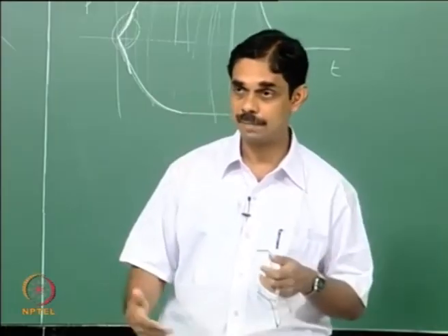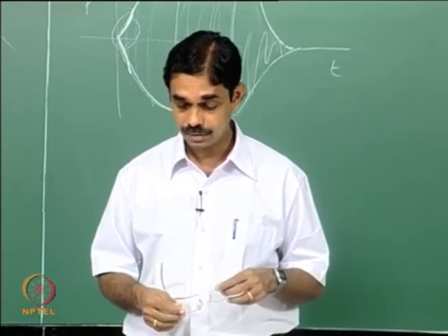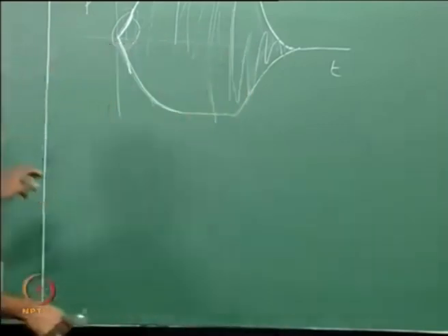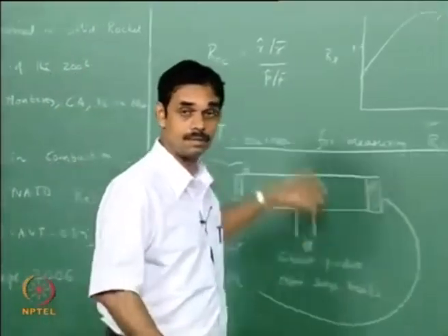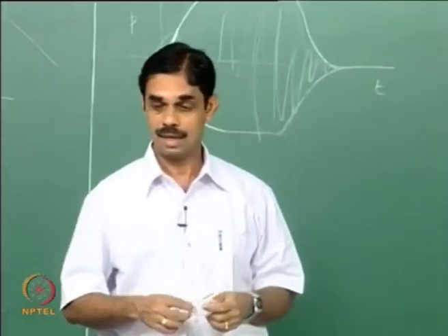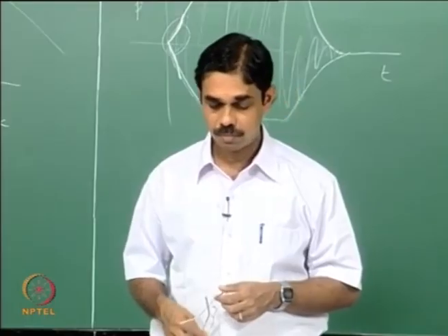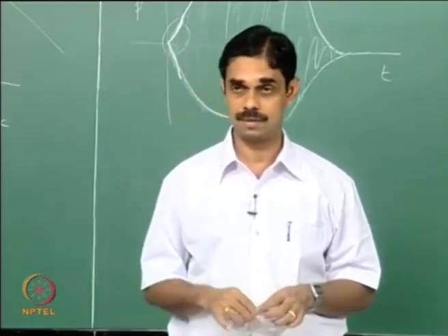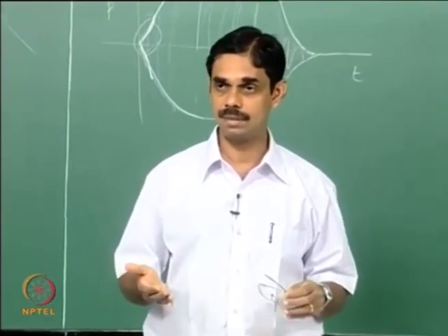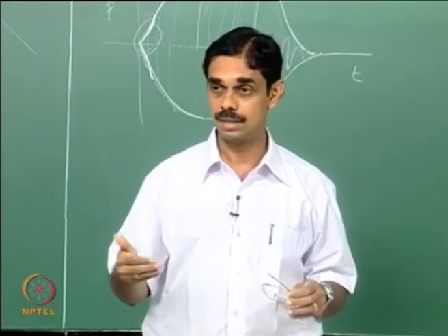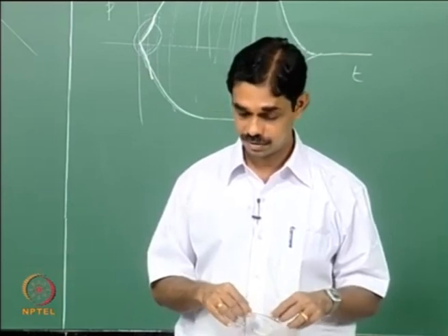And very coarse AP, again AP is ammonium perchlorate, gives instability, and the pressure coupled response function has a very strong dependence on P bar, so you must do elaborate testing. Propellants with a low pressure exponent will in general have lower response function. It is not that n is the same as the response function, but generally it is seen that propellants with lower n, this burn rate index exponent, will have a lower response function.